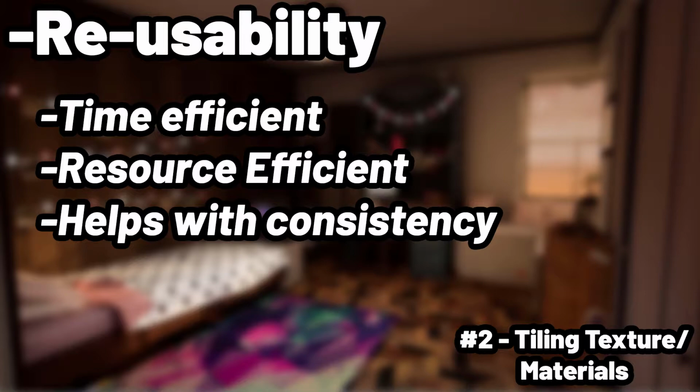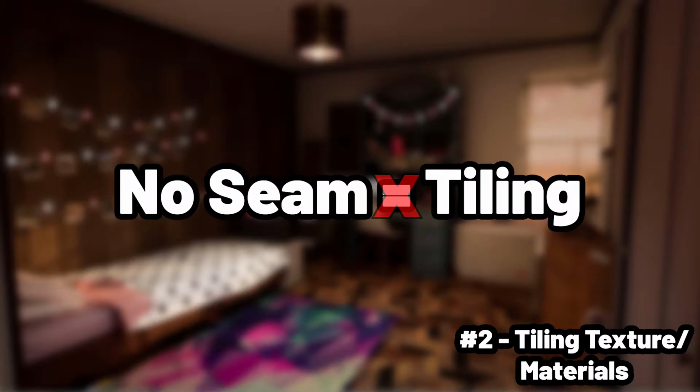You also want to make sure that you don't just have a tiling texture in terms of no seams. You also want a tiling texture in the sense that it has no extreme light or dark values, because when you can clearly see a difference, you can see the repeating pattern. Even if it's tiling, it doesn't necessarily mean the tiles hide. So keep an eye on your high and low frequency values and adjust them if need be. And then from there, you can use masks, like I explained in the previous tip, to help you create variety and also add decals to overlay on top of the material to break up the texture a bit.